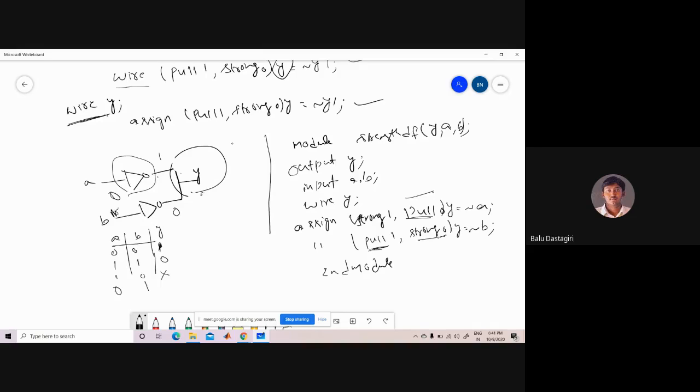For the NOT gate, the output is 1, that is the logic 1. Therefore, for the first NOT gate, the output is 1. Whose strength is strong? Similarly, for the second NOT gate, the output is 0, and for 0 the corresponding strength we have given is strong. So again, the two strengths are the same. Again, we are getting the contention resolution here. That means we cannot resolve the output even though we have assigned the strength.